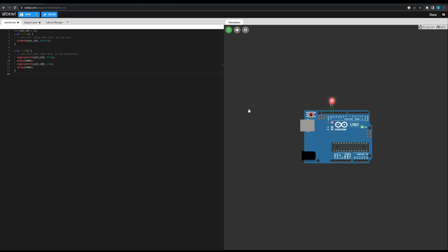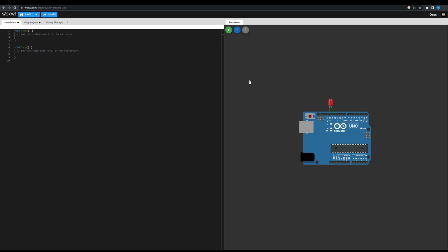So that was just a taste of what the Arduino board offers, and you can do so much more with it. So let me show you some other bits and pieces that you need to get started with Arduino programming. Similar to other programming languages, you can output variables and various other data types using the print line function with the serial port. So we want to do the setup for serial first. So we'll write serial.begin and add in the baud rate. You won't need to worry about what this number means at the moment, but just simply type serial.begin(9600), and then this will tell your Arduino board that now you're ready to begin printing.